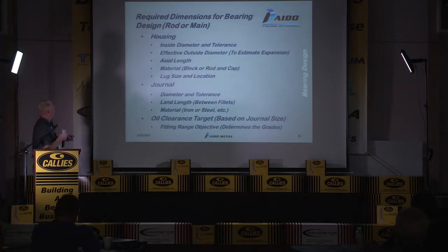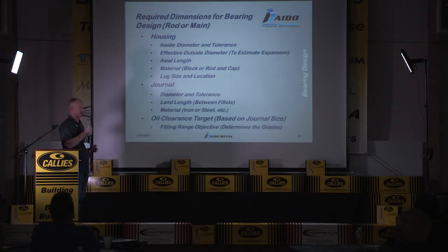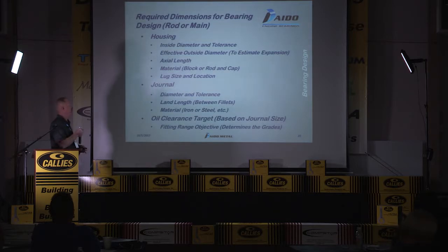These are just some of the bearing design factors that we look at when we're designing a new part or looking at different applications. The housing diameter and tolerance are very important to determine what grading is required for each application. The axial length, the material, lug size, and location. Also, one of the important factors is what kind of oil clearance is being targeted.